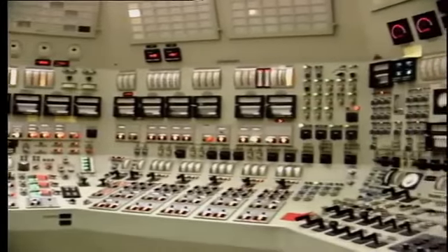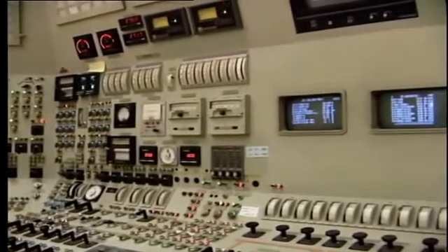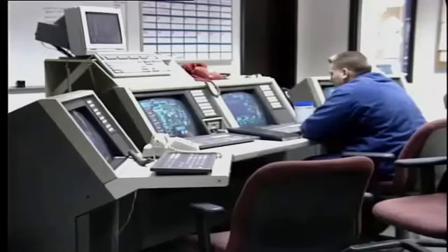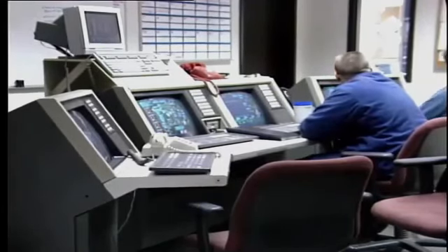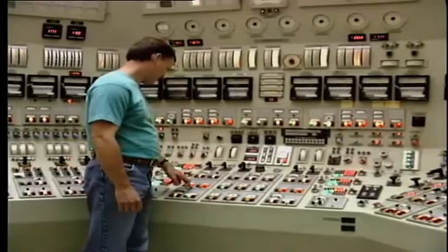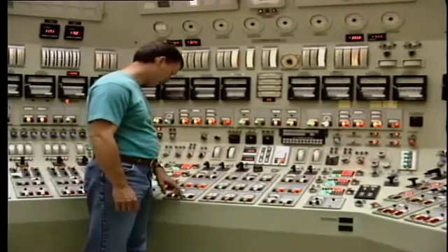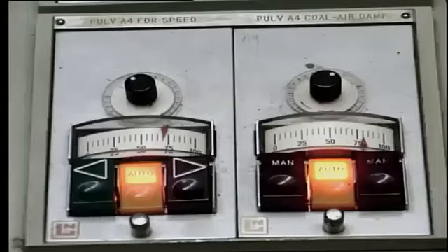We have already studied monitoring equipment, both the traditional control panel and the modern operator's console. In either case, the operator is able to stop and start equipment and make adjustments remotely, that is, from his central operating position. The operator can also manually adjust all of the major operating parameters, such as fuel input, combustion air, feed water flow, steam temperature, and so on. Of course, it's almost impossible to simultaneously control all of the many variables manually. Indeed, it is essential that the major operating variables be controlled automatically.